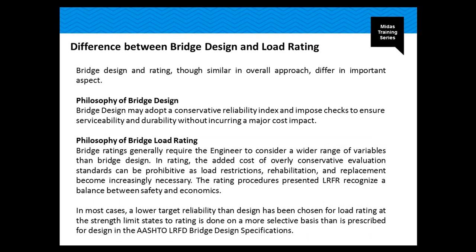Now, talking about the difference between the bridge design and load rating, they are similar, but they have different aspects. The philosophy of the bridge design is to basically adopt a conservative reliability index and impose checks to ensure the serviceability and durability without incurring a major cost impact.